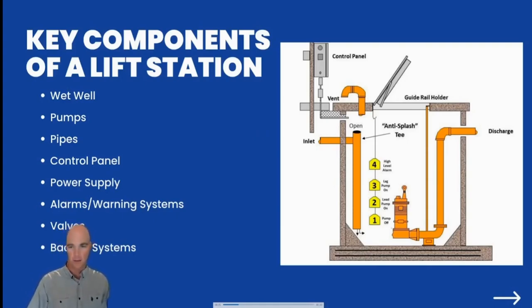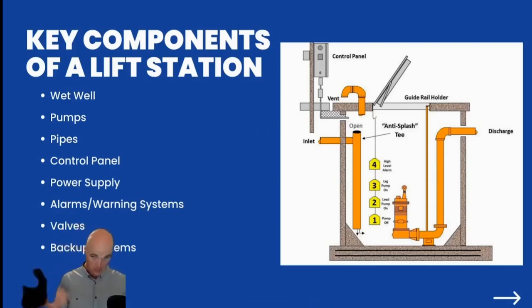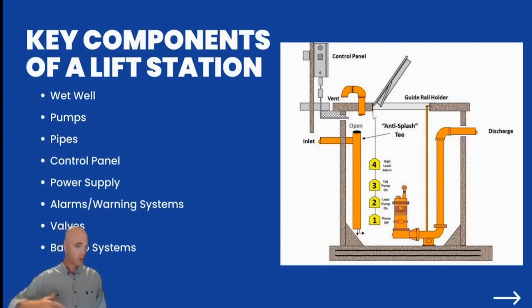We've got the pump itself. So right here is the mechanical device, the pump. It's run off electricity, and that's what's going to move the water up and down. In this image, the pump is actually in the wet well. Sometimes they have a suction intake, and then over here on the right, that's where the pump will be outside. There's different advantages to having it in or not. Sometimes, for example, the fluid of water will help keep the pump cooler and help with some of your efficiencies there. But having your pump outside of the lift station and not in all the sewage, it could not get caught up in different rags and stuff, or it's also a lot easier to maintain.